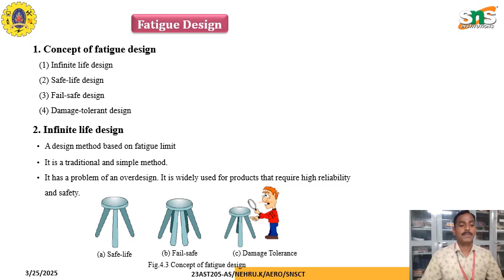Fatigue design. The concept of fatigue design has four components. First, infinite life design. Second, safe life design: even though it fails, it should operate. Third, fail-safe design: even though it gets some damage, it should tolerate operation. Fourth, damage tolerant design.